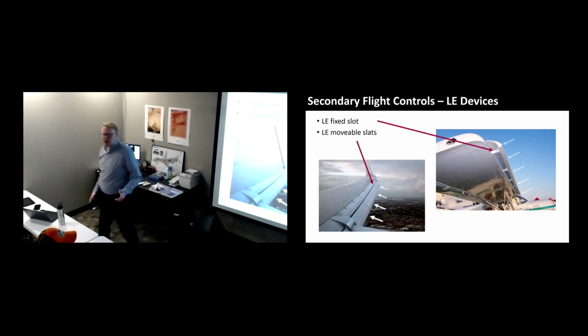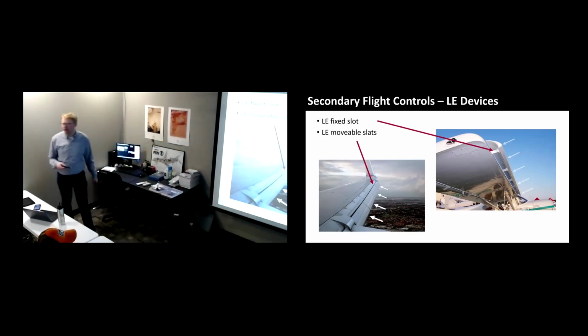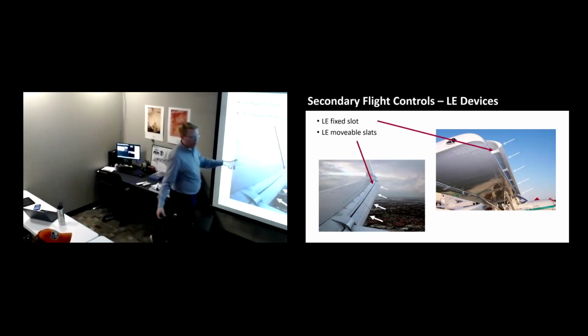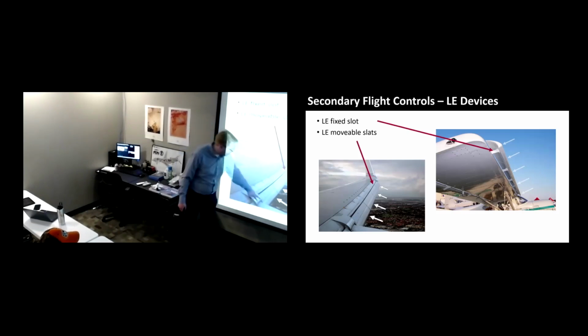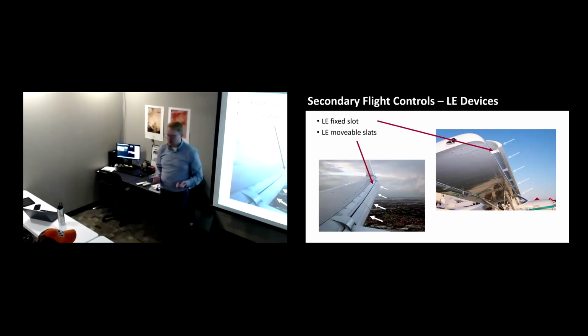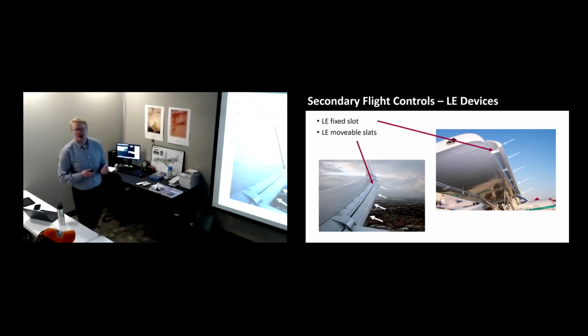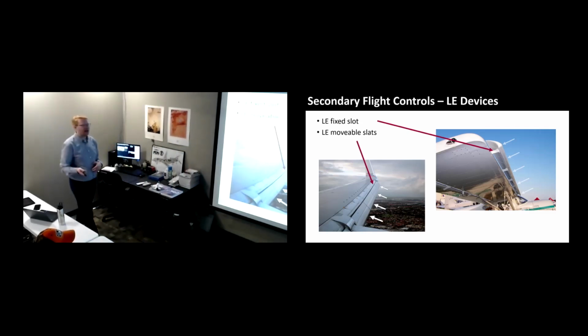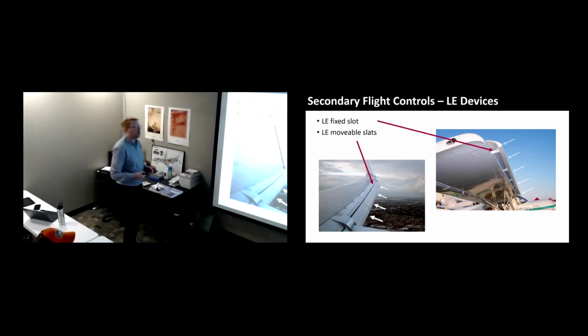You'll see the term energy adder device if you look in the physics world. What we mean is we're adding energy, which is going to be airflow, and more lift. So if you can add more air into this wing, it gives it more air to work with and more lift to produce. That's all this is doing. This is directing more air further after the leading edge. It's hitting the leading edge, bringing it out, allowing more air to come up over it. This allows us to fly at higher angles of attack that would not reach the critical angle of attack earlier. It delays your stalling speed essentially.